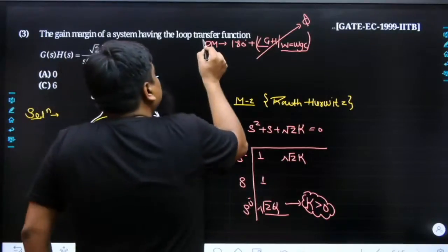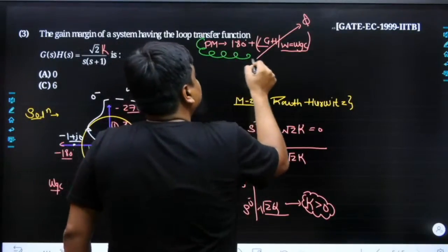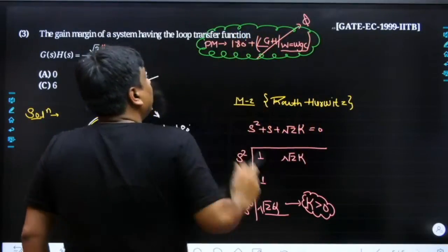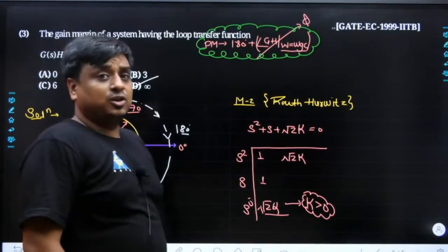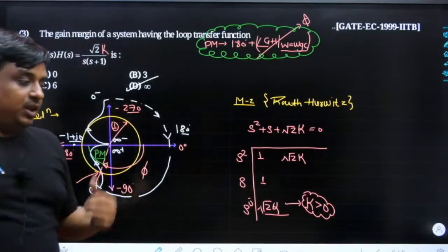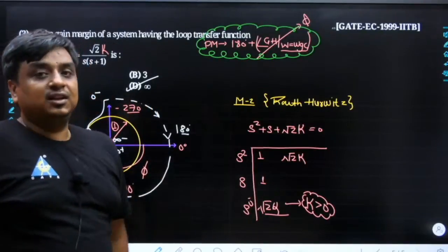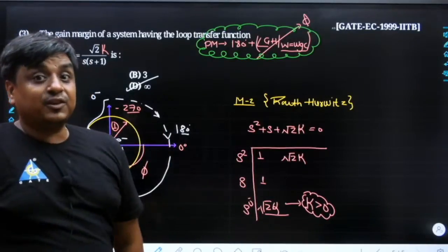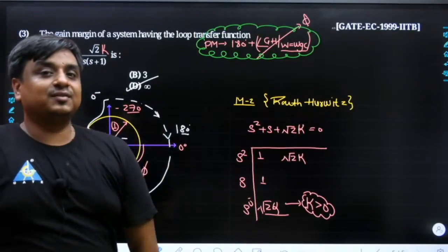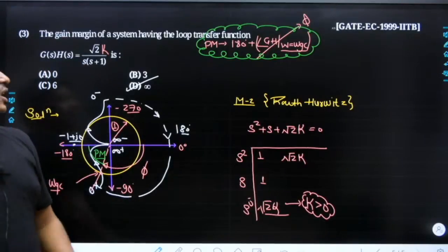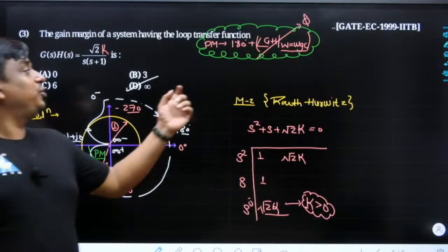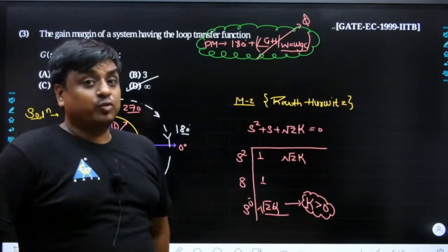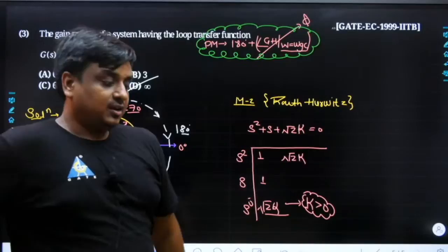So I would say now nobody should have to learn this formula by heart. The phase margin is 180 degree plus the angle offered by the system at omega equals omega Gc. I have also seen many times students memorize it, and have doubts: while calculating PM, we use the reference of omega Gc, so why don't we take omega Pc, and while calculating GM, why don't we take omega Gc? That is utterly wrong.